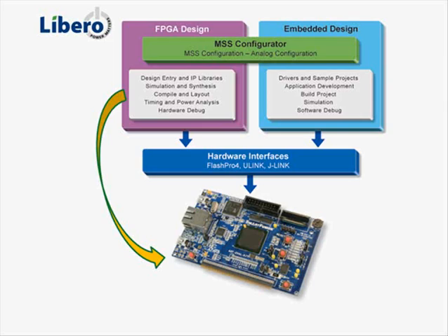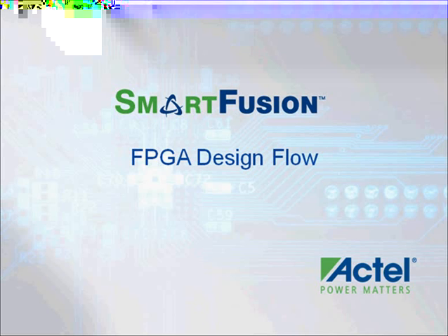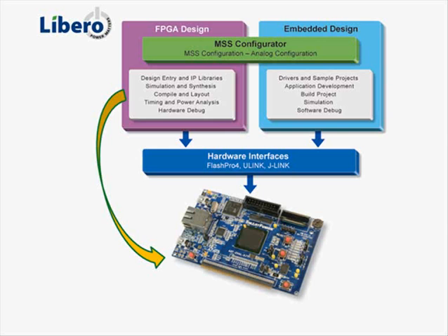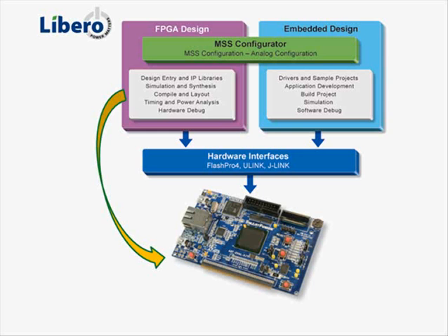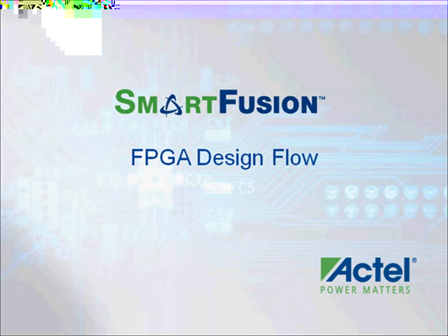This video covers the basic steps of creating a SmartFusion hardware design using Libero IDE. It will show you how to create a SmartFusion project and configure several MSS (microcontroller subsystem) peripherals, including the fabric interface peripheral that allows you to connect the MSS to other logic blocks on the SmartDesign canvas. The logic blocks can be cores from the Libero IDE catalog or user-created HDL blocks that have been imported into